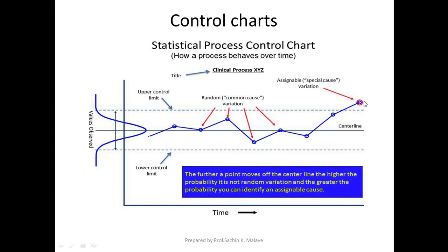Some one of the components has hardness which is beyond the upper control limit also, isn't it? So it may be around 193 BHN, let us say. So it is going outside this upper control limit. So you can say the variation in the hardness is right from 170 to 193, a 21 BHN variation. Now with the help of this quality control chart, we can find out whether the process is going as per the plan or not. That can be easily understood.